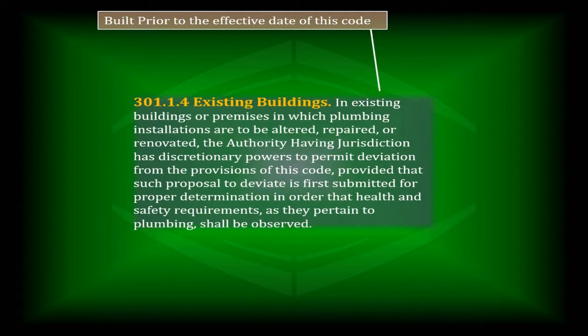Look, what they're telling you here is when it comes to existing buildings, the new code updates are not meant to render a building unusable. They're meant to give us all a set of standards that we can follow. And when it comes to existing buildings, if something was considered to be up to code in a previous code cycle or in the code cycle that it was built during, then unless you mess with it, alterations, renovations, repairs, you're not going to be made to bring all of this stuff up to code, right? That would just be impractical and, of course, a burden on the end user.